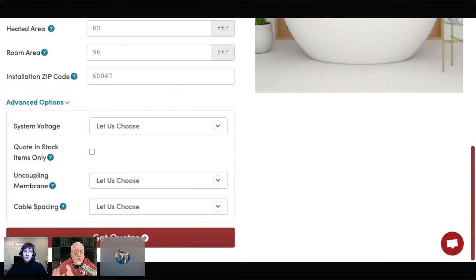I'm thinking of doing a 3-season room. Here's what you should do. Try to do tile if you can, because you're going to get more heat out of tile. You can do the others, but just keep in mind you're using a throttled back product, that we are throttling back because the manufacturer of the laminate says you can't go over 84 degrees. Okay, fine, we'll do that. That's why we ask these questions. Yes, that is a really good point. Awesome.